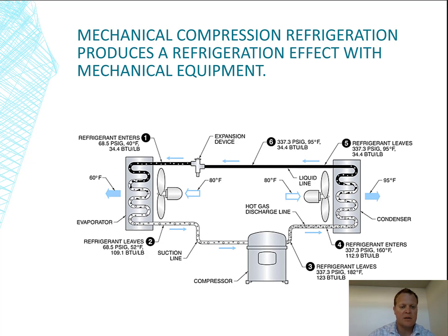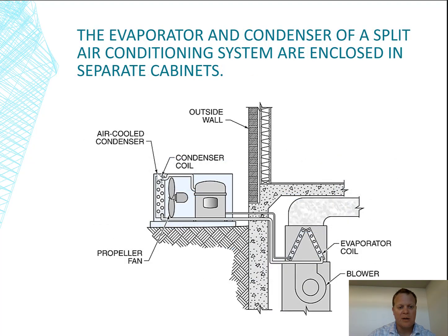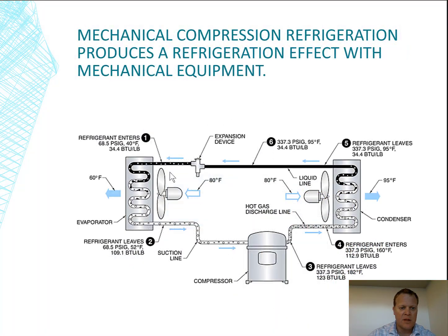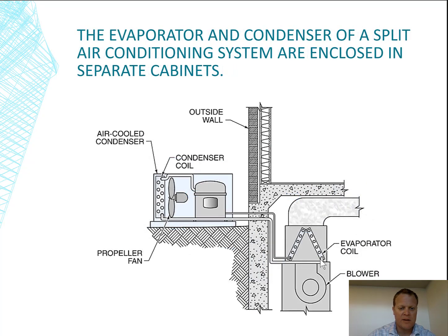So we're seeing that happen here. High pressure gas coming like this, turning into a liquid, being condensed, liquid hits this expansion device, which is not shown, somewhere down here, and it starts to boil.